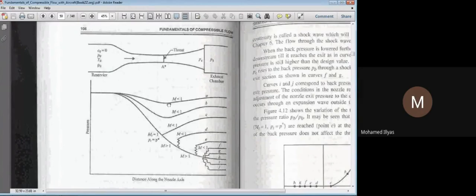After that, in the divergent part, what has happened? Pressure is increasing, correct? So that means velocity is decreasing in the divergent part. For another position of the valve, there is a further decrease in pressure, that is a corresponding increase in velocity. After that, again the pressure is increasing. Instead of a decrease in pressure in the divergent part, pressure is increasing. Pressure should not increase in the nozzle. If it is increasing, the nozzle will not serve its purpose. We will get a decreased velocity.